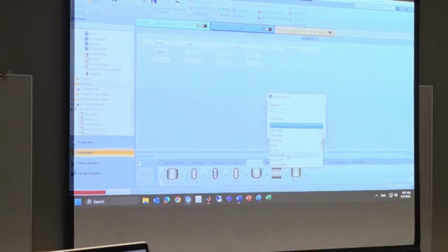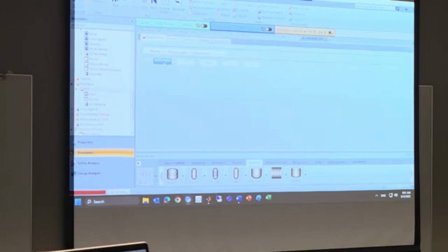We use the power law type, so please choose power law. Same procedure, we can define two reactions here. Now I can request ethanol, acetic acid, ethyl acetate, water. We know the stoichiometric coefficients.